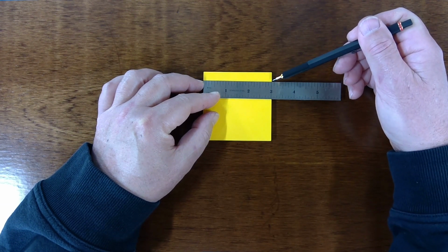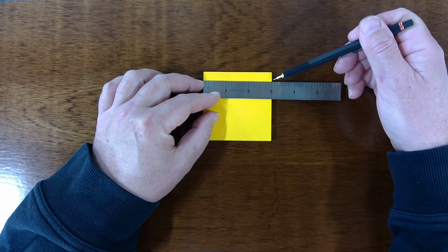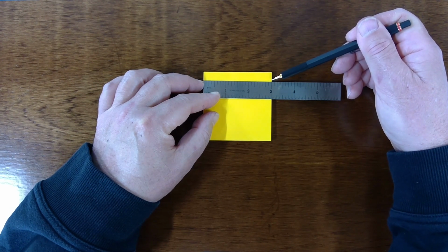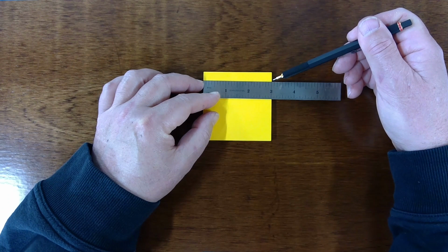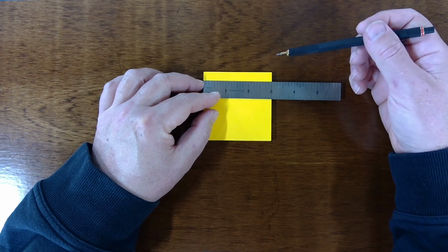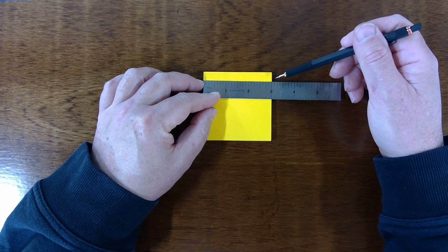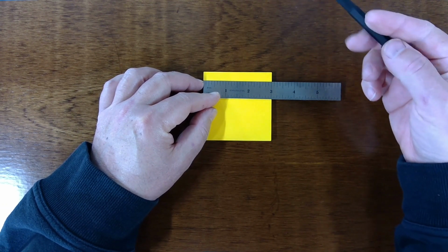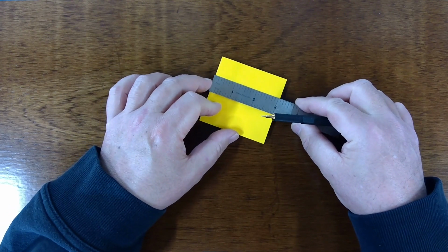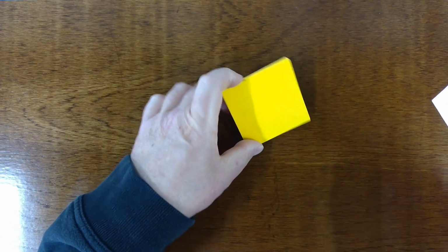Like, say, plus a millimeter and minus a millimeter. So then if it was plus a millimeter and minus a millimeter, the range on that, the 1 millimeter over and 1 millimeter under, would be 2 millimeters. So we would say the tolerance is 2 millimeters. So that's the basic idea with tolerance. We can't make something exactly, so we have to specify a range of dimensions that are acceptable.